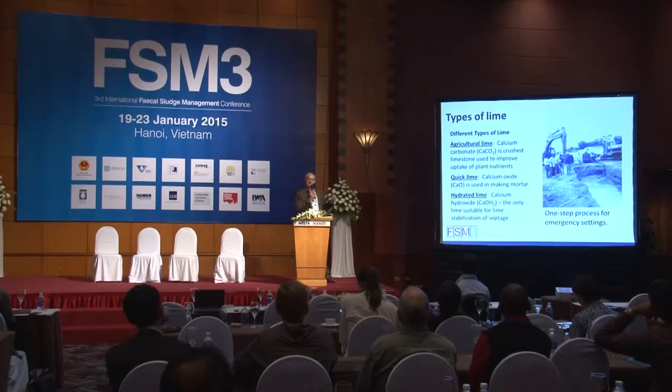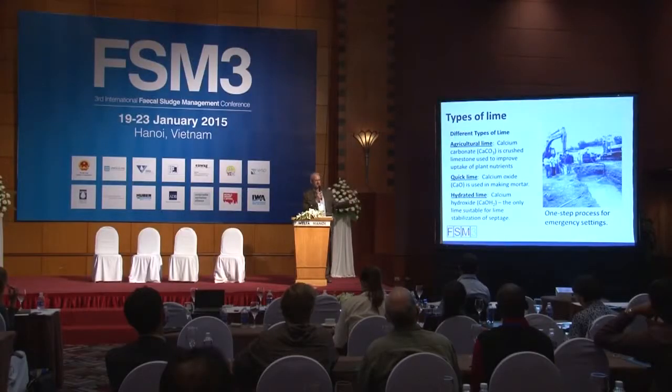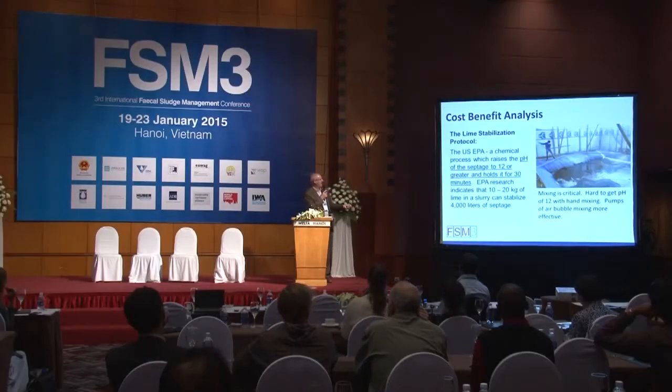Now, in an emergency situation, if you can get 20 guys and gals together with shovels, you can dig a trench pretty quickly. Here, these guys had access to heavy equipment, which made that easier. But it's basically dumping the fecal sludge into the trench, mixing the lime in, and then after a few days, covering that trench and digging another trench. This is a very simple, low-cost, easy, fast method of treating and disinfecting your wastewater.